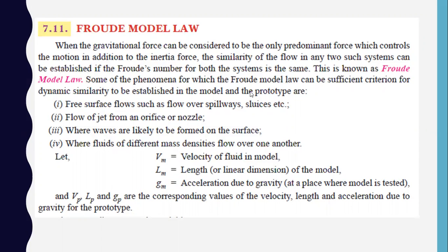Some of the phenomena for which the Froude model law can be a sufficient criterion for the dynamic similarity to be established in the model and the prototype are: first, free surface flow such as flow over spillways and sluices; flow of a jet from an orifice or nozzle; where waves are likely to be formed on the surface; and where fluids of different mass densities flow over one another. So these are the Froude model law applications.